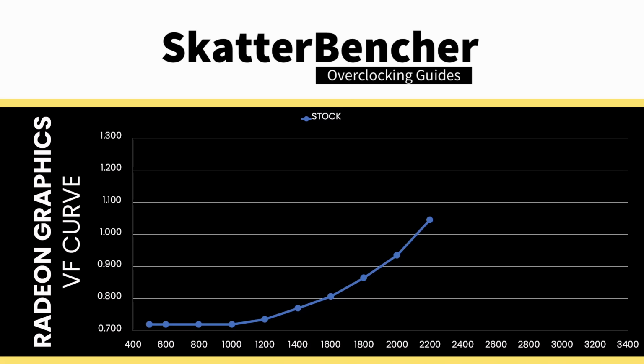The Radeon Graphics also have their own voltage frequency curve. At 2.2 GHz, we need about 1.045 volt. The lower voltage limit is 720 mV and the upper voltage limit is 1.25 volt. We hit this limit at about 2.5 GHz. Any frequency higher than 2.5 GHz is also restricted to the same 1.25 volt.